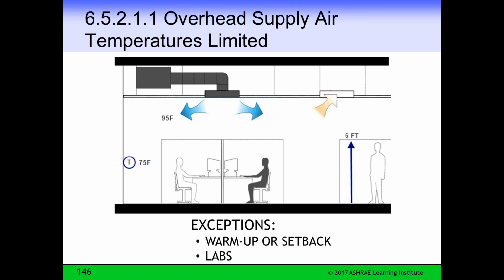Now, we looked at that. They have some other requirements. They say that at 4 foot from the ground, the velocity of the air has to be 100 feet per minute. This is a very particular requirement, especially that 100 feet per minute. With ASHRAE 90.1, we normally would try to write a companion rule that would meet ASHRAE 62, but we decided in this case we couldn't.